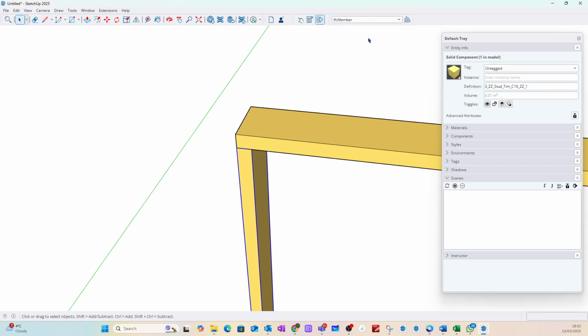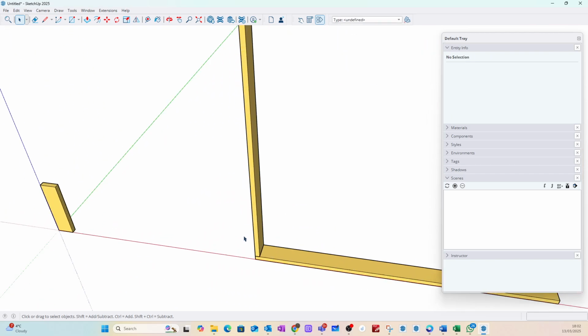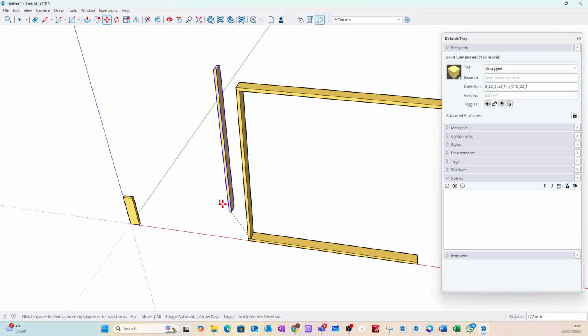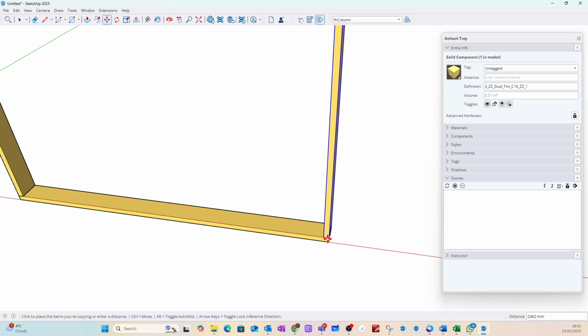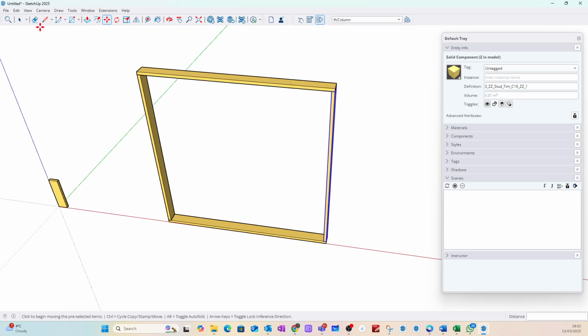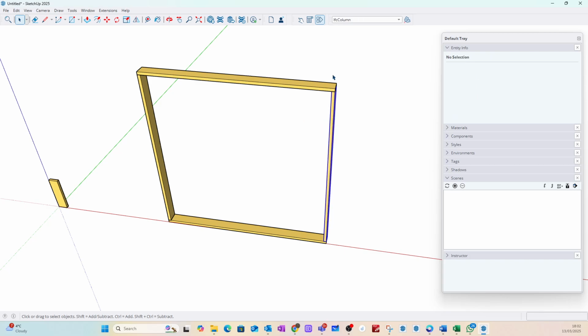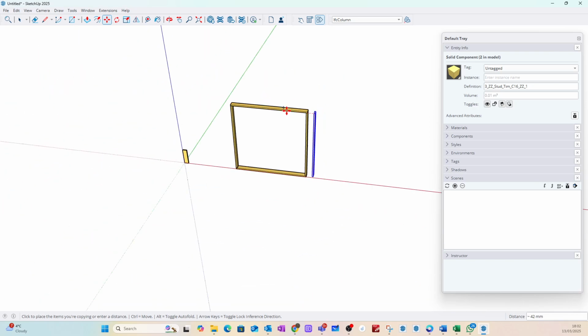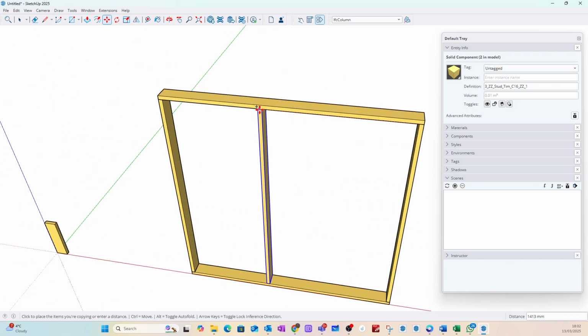And here, it's not a member, it's actually a column, IFC column. So we'll go in here and we'll go IFC column. Perfect. We'll grab that stud, we'll move it along, keep the original where it was, place it there. Absolutely amazing. Now we can grab that stud again from the middle this time, and we'll keep the original, and we'll move it along to the center,